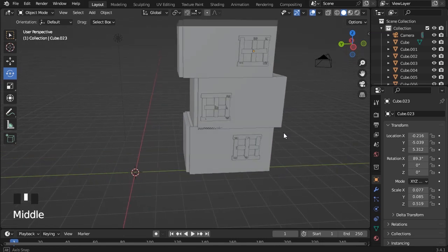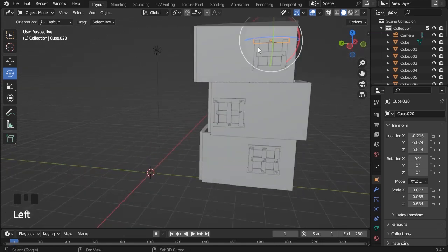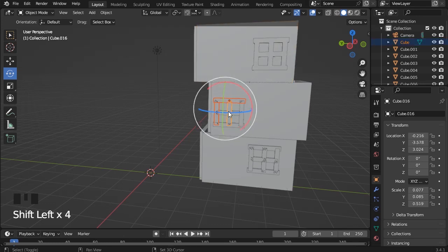And the other tool is a shortcut. You press Shift, then you click these things, and then you press Control J. Now this entire thing is connected. Look at that, it's just beautiful. And make sure, okay, because there are common mistakes. So some people will do it like this.